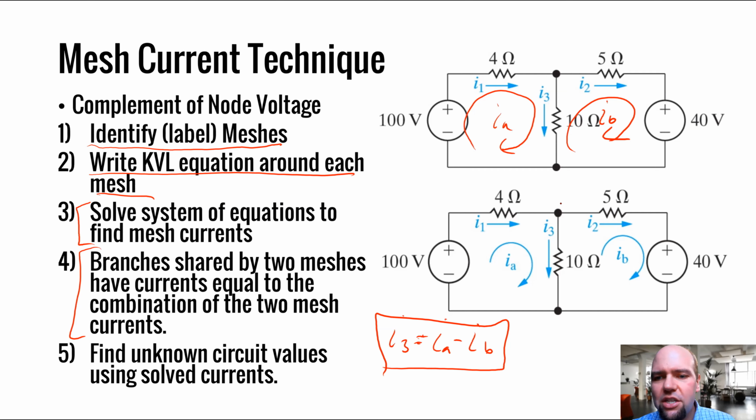Well, let's think about just this node and apply Kirchhoff's current law. If we were wondering, based on this node, how much current was flowing down here, what would that be? The current flowing out of this node would be the current flowing in minus the other current flowing out. Or another way to put it is, if we did a Kirchhoff's current equation at this node, and we did the sum of the currents flowing out, we could say negative I1 plus I3 plus I2 equals 0.